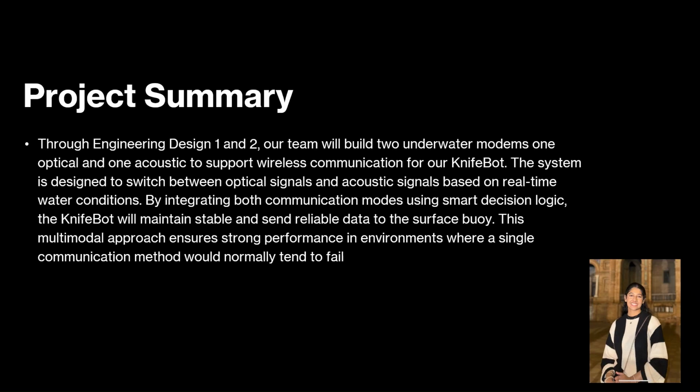Since optical works best for fast, short-range data, while acoustic communication is better for long-distance or murky environments, by combining both systems using smart decision logic, the knifebot will maintain a stable and reliable connection with the surface buoy. This multimodal approach ensures strong performance in an environment where a single communication method would normally tend to fail.